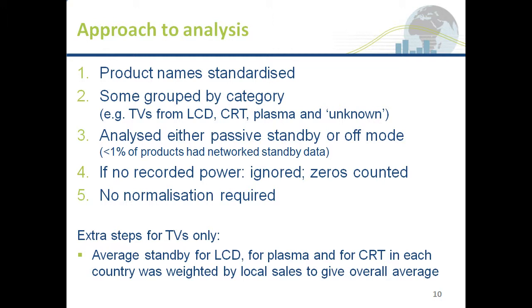Now, in terms of the statistical analysis and the calculation of averages, if there was no recorded power figure against any particular product, then that was ignored. But for many products, there was actually a 0 recorded in the data set against the standby power, and we took this to mean that the reading was below the resolution of the meter that was used, and so we took it as a real reading and we counted that 0 as part of the calculation of averages.